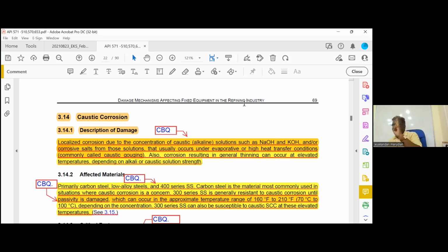See, generally caustic is used in industry for two purposes. One is as a catalyst. We will add it to water. Another one is for neutralization. If you want to neutralize the acid, they will add caustic. So acid can be neutralized by the caustic. Here we are adding it as a catalyst. Now, if it is properly mixed with the water, there will be no corrosion.